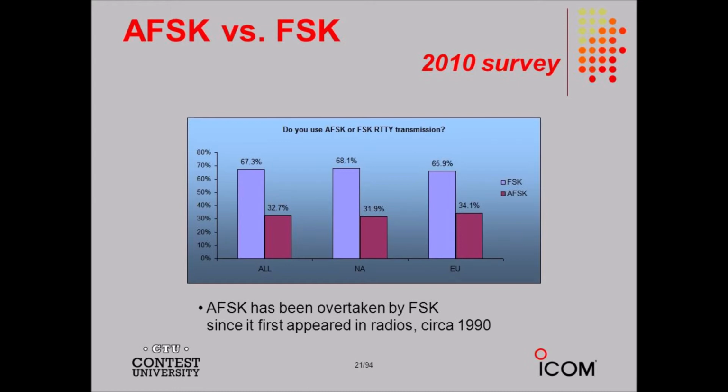We can almost completely suppress the carrier in an AM signal using a balanced modulator, an amplitude modulator amplifier using two transistors with the inputs connected in push-pull and the outputs connected in parallel, as shown in figure 25.5. This arrangement cancels the carrier wave in the output signals, leaving only lower sideband and upper sideband energy.